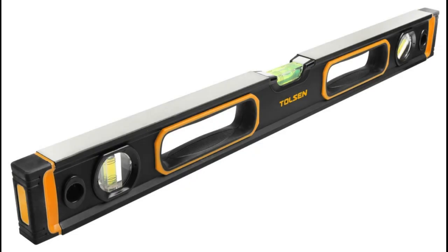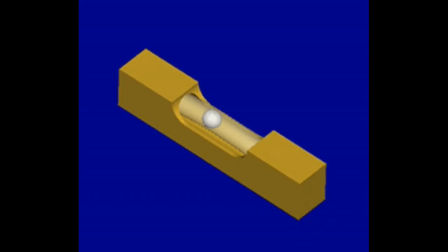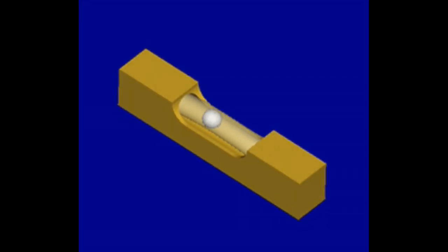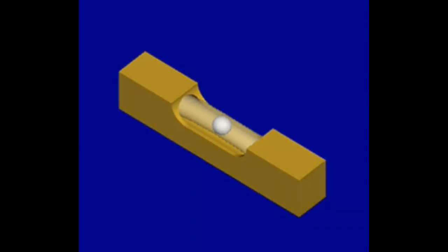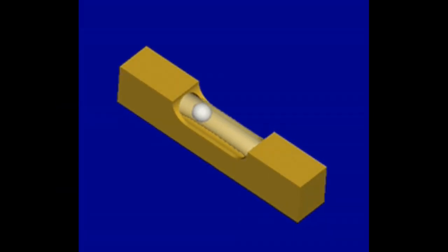Next is spirit level. An engineer's spirit level, also called machinist level, is generally used to level machines, although they may also be used to level large workpieces on machines such as planers. Using gravity as a reference and checking a machine's axis of travel at several points, the level is used to ensure the machine's axis is straight.